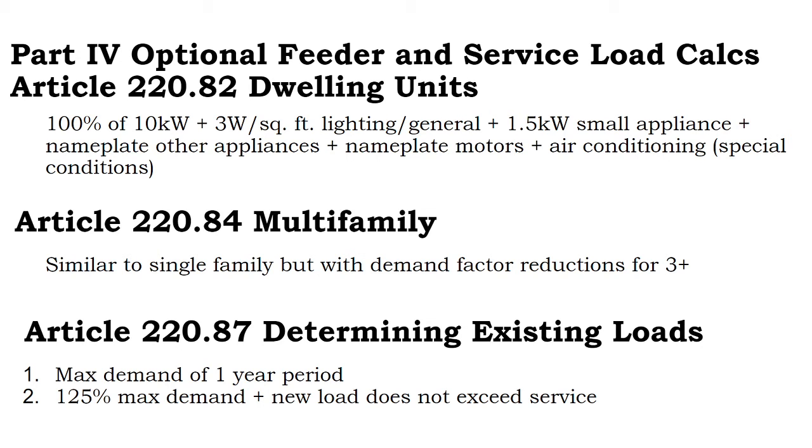Or you can collect the load data for 1 year and use that load data. And where that might start to get useful is larger houses where you might have to be installing 200 amp service panels to land all the breakers. And you say, well, do I need to have 400 amp service from the utility?